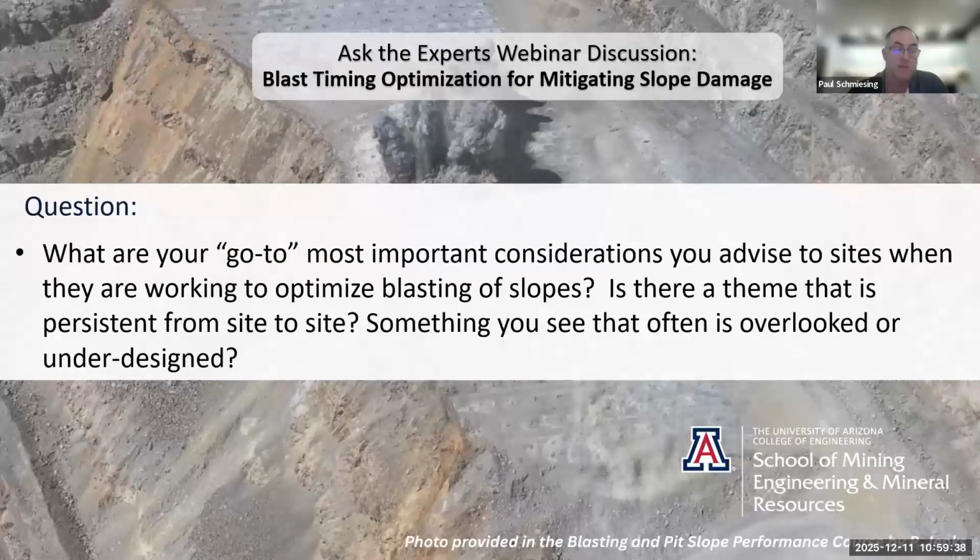And so again, you can see from the seismograph, the blast is going good, and then all of a sudden it gets to the corner where because they didn't add an extra hole in that corner, or add an extra hole in the corner and kind of space that little bit of extra burden out, distribute it.